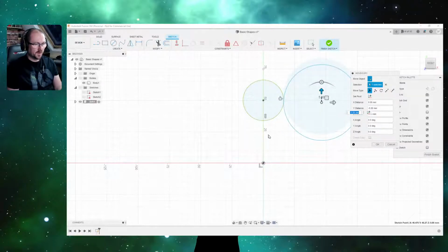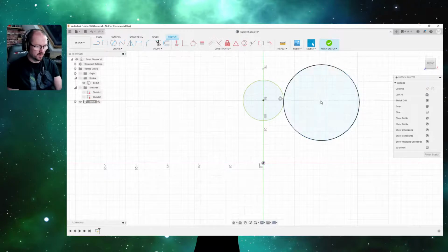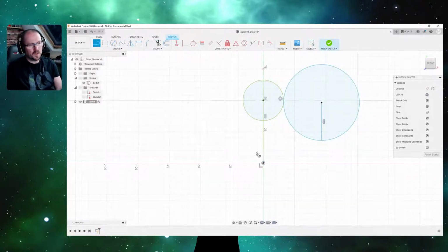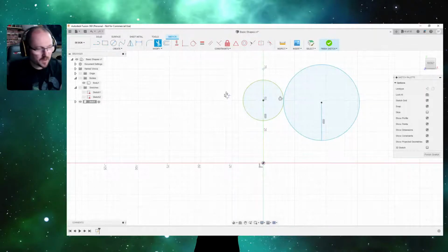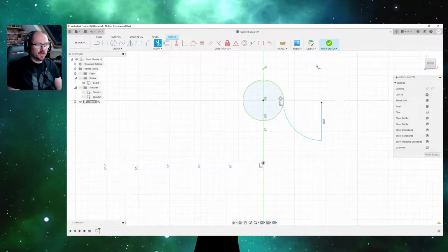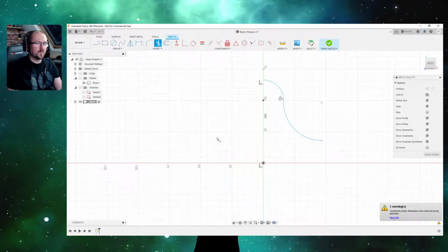Okay. And now I'm going to create a line from the center to here. Let's click OK. And you'll see why I'm going to do that. I'm going to start trimming. So if I click T on my keyboard, I get a pair of scissors on my cursor. And I can just click away, and we'll reveal this new shape, right?